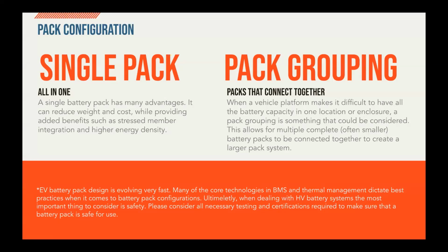In this example, it's a very, very bad idea to do what I just described. It's much better to do a battery pack grouping instead of a module grouping this way, because the modules, the way people use them, don't have any proper power distribution, and they are very, very unsafe. And so those 5.3 kilowatt hours, if in an enclosure with proper power distribution and then connected together, could provide a very safe, properly designed pack grouping.